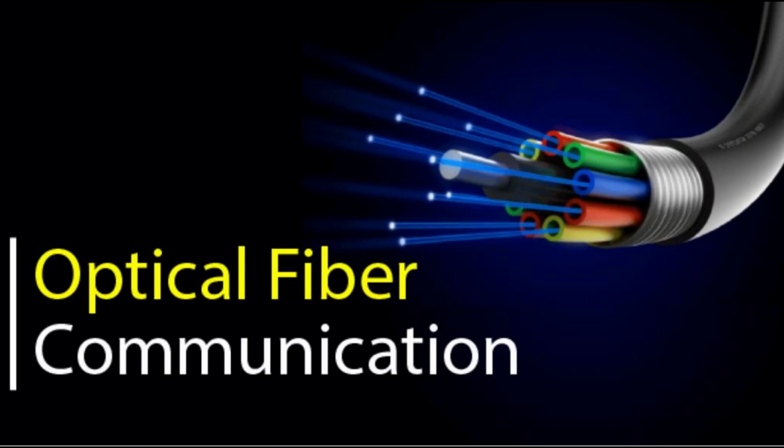Multi-mode fiber. Multi-mode fiber is used for shorter distances because the larger core opening lets light signals bounce and reflect more along the way. The larger diameter permits multiple light pulses to be sent through the cable at one time, which results in more data transmission. This also means more possibility for signal loss, reduction, or interference. Multi-mode fiber optics typically uses an LED to create the light pulse.